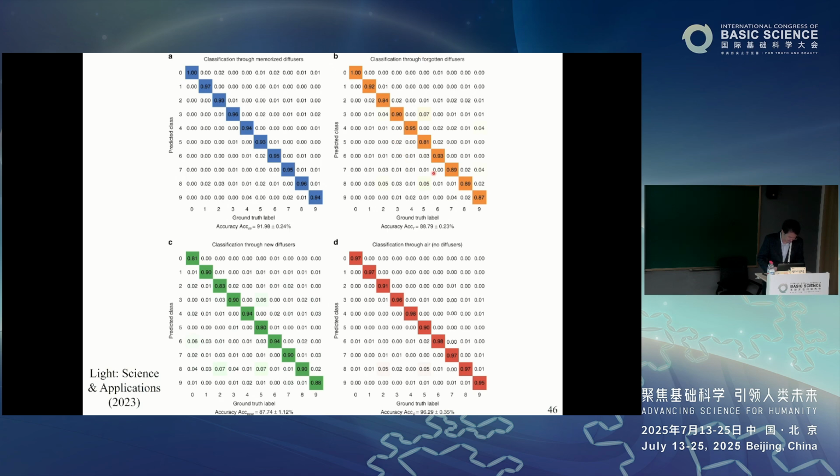The slides show the experimental validation of the spectrally encoded single-pixel vision system operating at terahertz wavelengths. The 3D-printed broadband diffractive network consists of 3 phase modulation layers, visualized at the top of the image. The bottom of the image illustrates the principle and physical arrangement of the system, which is essentially a terahertz time-domain spectrometer setup with a broadband pulse illumination serving as the input.